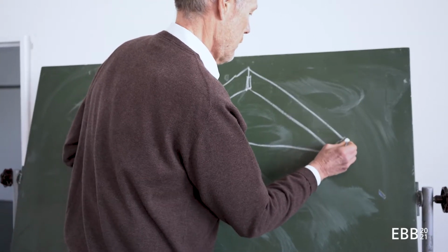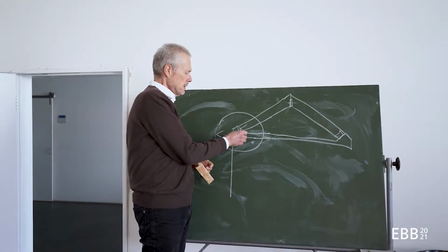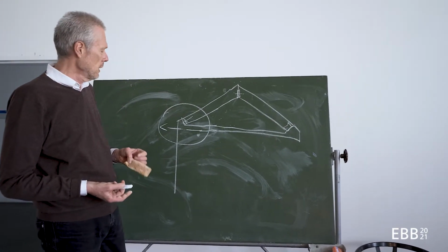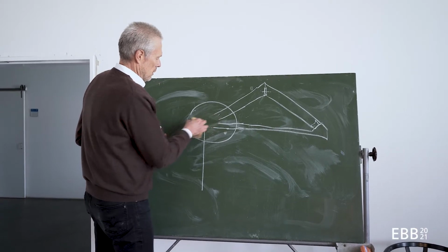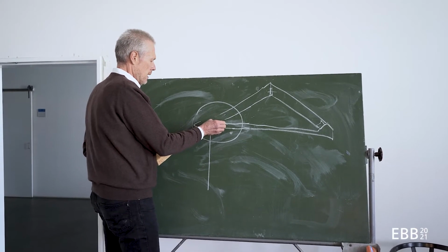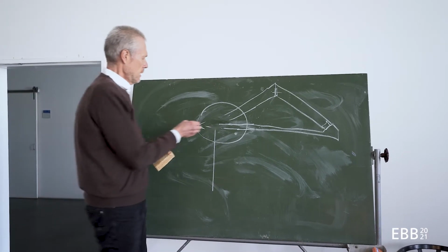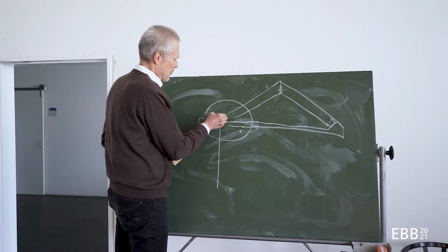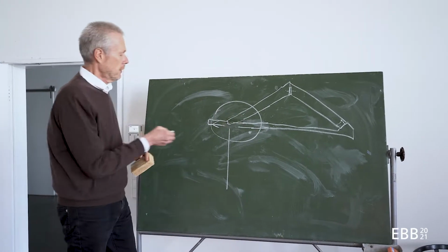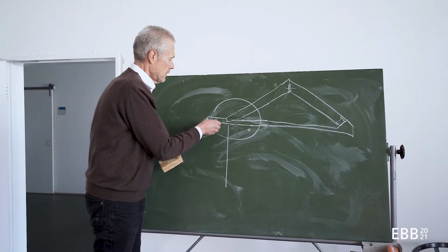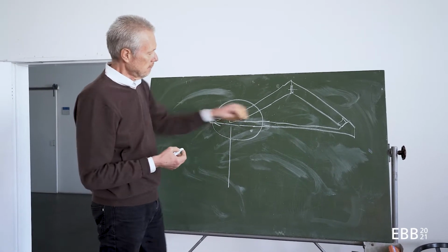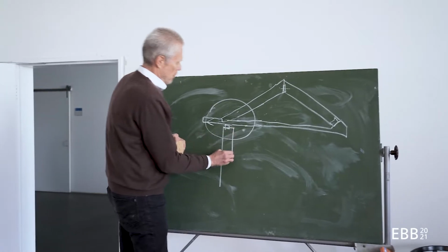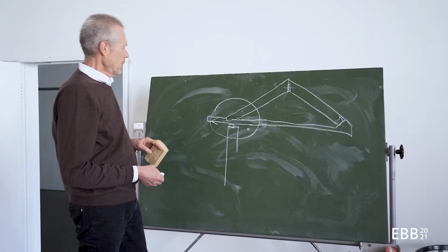What I've been drawing here is a concrete floor slab and wooden roof construction. I could use beams as well, and then I might have a step joint here to transmit the load of the rafters into the ceiling beam, and the ceiling beam would lay on the masonry in one way or the other.